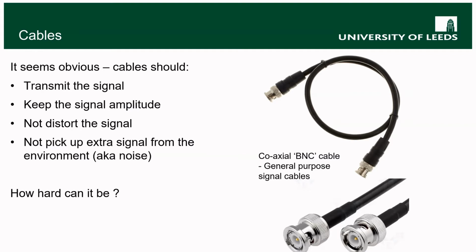On the connectors at the end you've got the central pin, which is the middle conductor, and the white around that is the insulation between it and the outer black conductor. And so a BNC cable is passing two signals, two conductors on the one cable, as opposed to the banana plug, which only had the one conductor per actual physical cable.